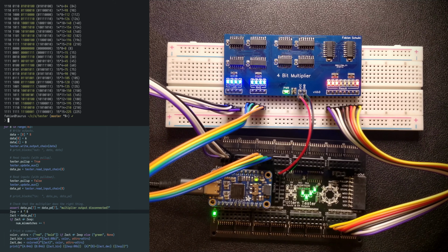And there are a few pretty clever algorithms for the case where you have a description of how your hardware looks like. So you have a description of your AND gates, your OR gates, your chips, and how they're connected. There are algorithms to systematically find certain classes of mistakes that can happen and that can detect those. And in the future, we might get around to actually toying around with something like that. But I think this is good enough for now. And for most PCBs that we want to test in the near future, it's actually going to be sufficient if we can just write a Python script and apply some interesting inputs and check for the outputs.